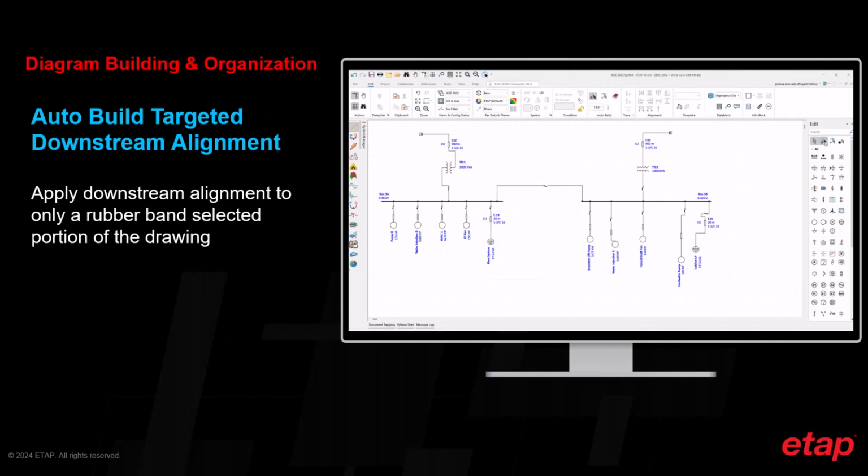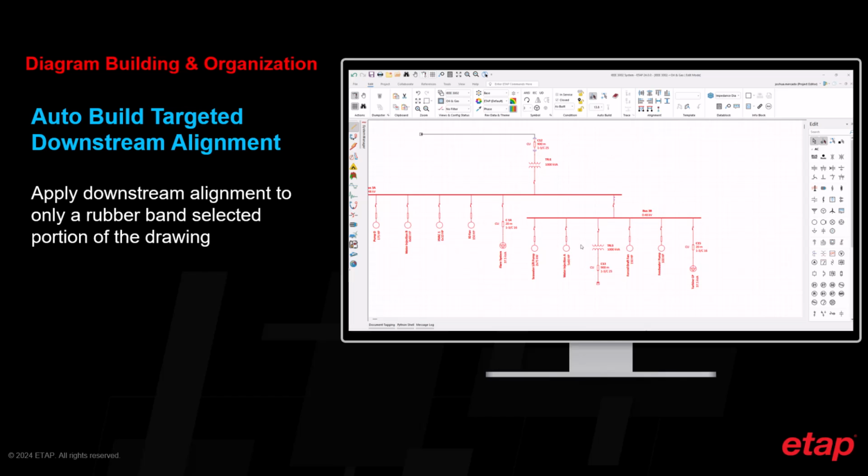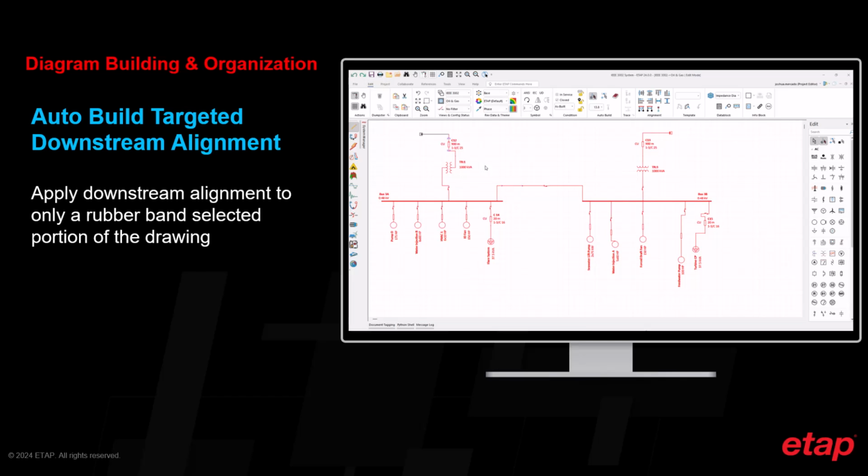Auto-build downstream alignment was a big step towards automatically arranging the system. However, it was not well suited for looped or multi-source systems because the operation assumes all connections below the selected anchor should be radially placed. To address this, targeted downstream alignment was added, meaning you could selectively specify the sections of a meshed system to arrange. Select the desired connected elements to align, then hold Ctrl and select the last anchor element. Perform the auto-build downstream alignment to see the targeted alignment in action.